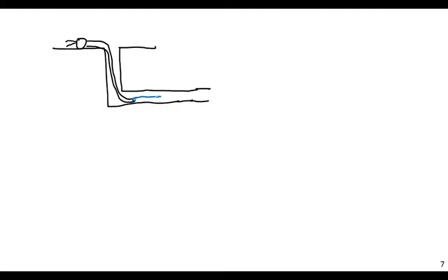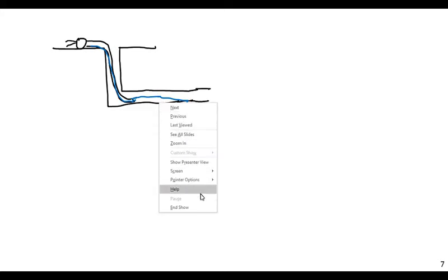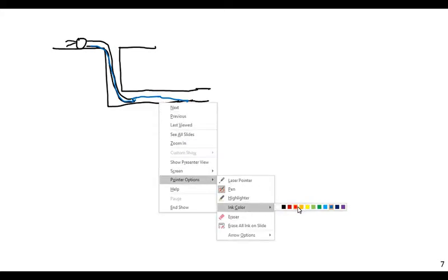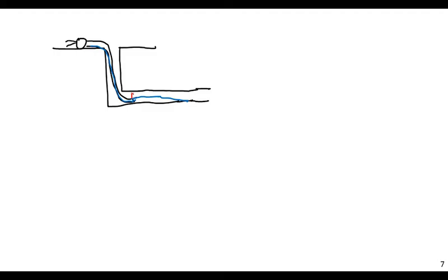Maybe at the lowest point in your mine, you have a pool of water that develops, and you just pump water up here. Now, again, what's forcing the water to go up the pipe in this arrangement is not actually the pump. What's forcing it is atmospheric pressure. There's P atmospheric pushing down on the pool of water here, to prevent a vacuum from forming inside the pump.